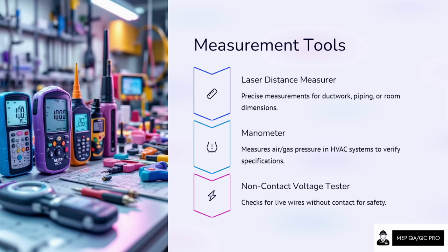Like when you want to check the bottom of the duct as per the drawings, whether they installed it at the right height. If the duct is at a very high level, for sure you cannot go there, and it will waste your time using a ladder or scaffolding. But through the laser distance meter, you can easily identify the ductwork installed at height, or the pipe size.